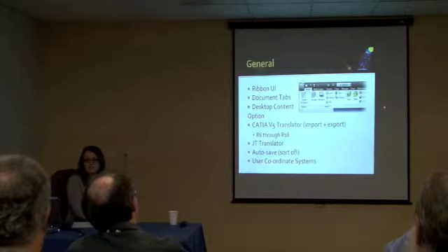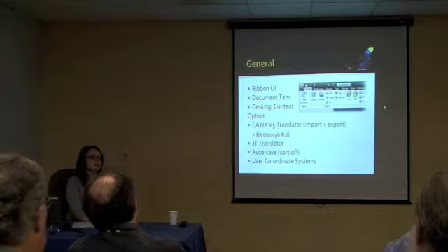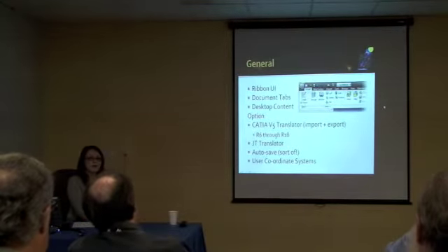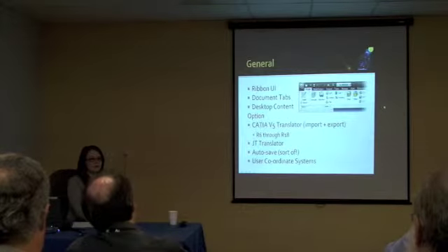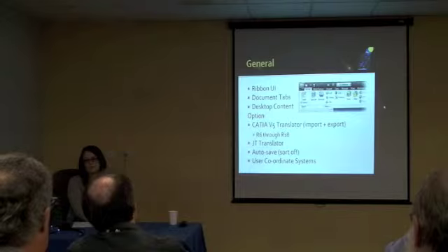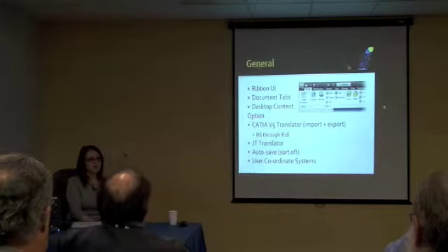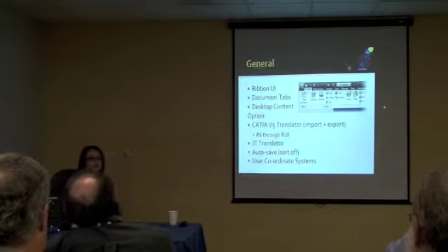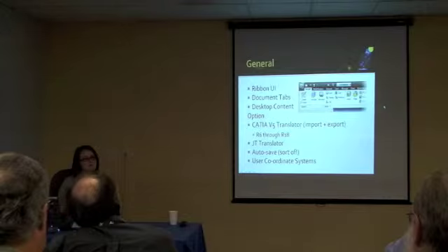Another general enhancement is the desktop content option. How many of you are single standalone users? Yeah? How many of you are sick to death of installing the Vault server to run Content Center? Okay, desktop content option addresses that. So you don't have to install the ADMS, the Autodesk Data Management Server, to run the Content Center if you don't want to anymore. You can just install this very light version called desktop content. It installs the databases on the machine and just hooks into them when it needs them.